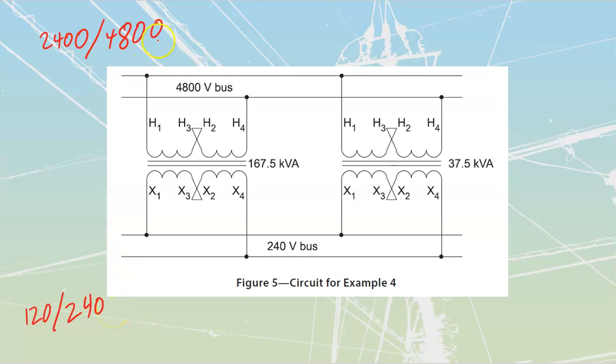If I'm going to connect it to the higher voltage, the 4800 volts, then what I'm going to need to do is a series type of connection. That's why we have these things crisscross. So we can either take them up to the same lines or we can series them together like this.